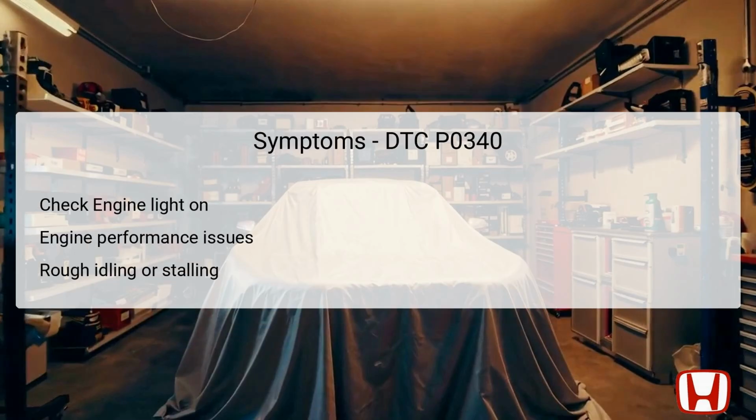When DTC P0340 is triggered, drivers may notice several troubling symptoms. The most immediate indicator is the illumination of the check engine light on the dashboard, prompting concern from the driver. Furthermore, one may experience significant engine performance issues, which might manifest as a lack of power, especially during acceleration.